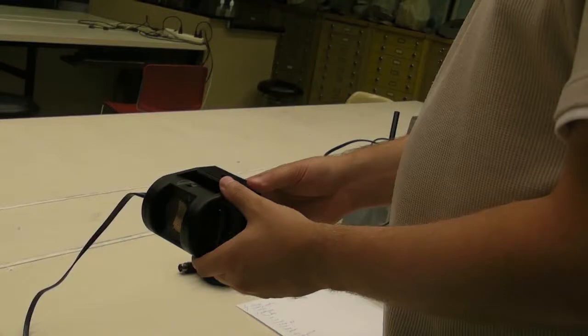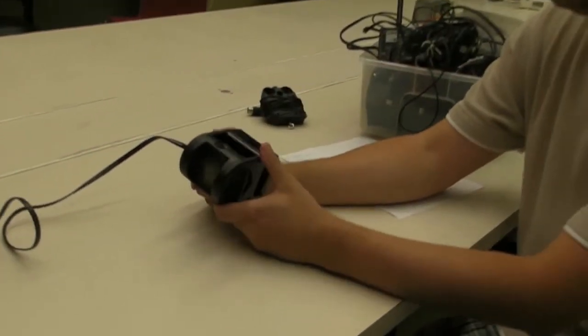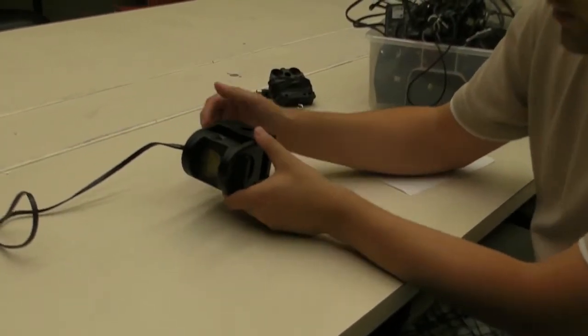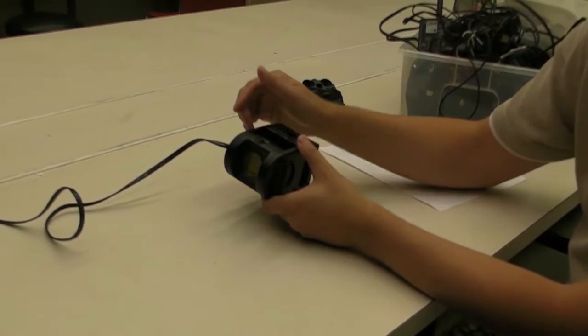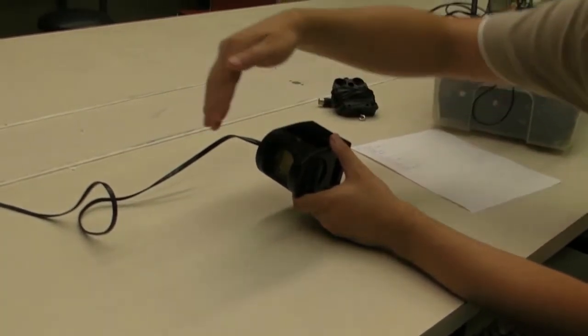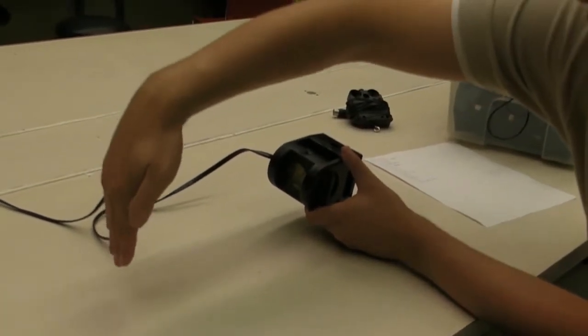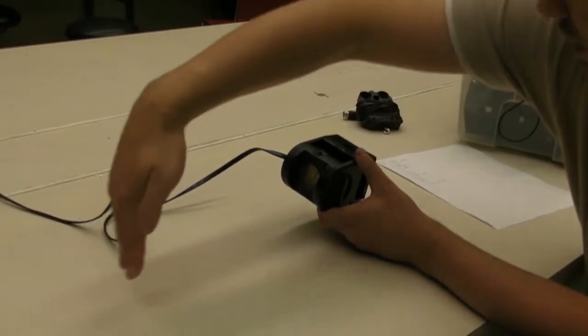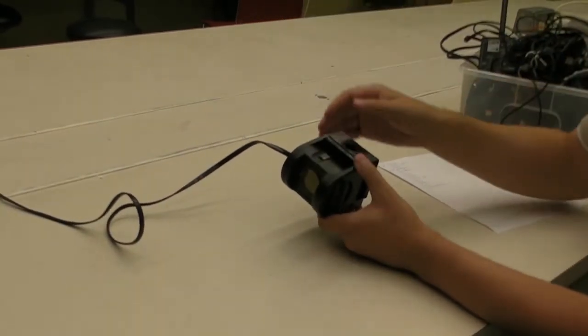This is referred to as a motion sensor, but might be better called a position sensor. It reports the distance between the flat surface on the sensor and the nearest object to it. It works by emitting an ultrasonic pulse from the flat surface and detecting how long it takes to return after bouncing off of a target. Note that it has a minimum distance of 15 centimeters.